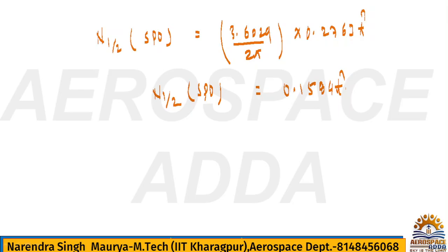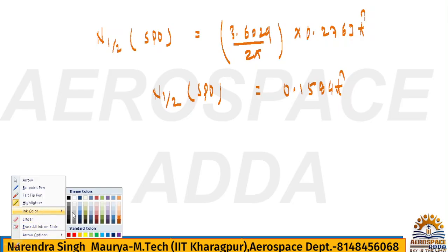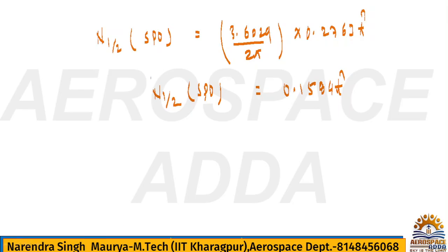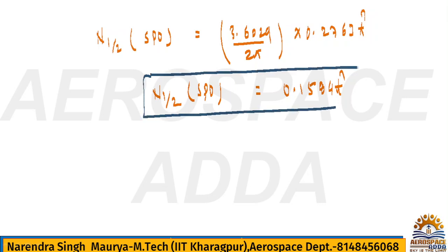Once details of the airplane like mass, density, velocity and all those things are given, then you can write the value of T cap also, but it is not given, so you can keep this in the same function. All right, this is done. All three values you have calculated: time period, time to half, and number of cycles to half, but this is for the short period oscillation.